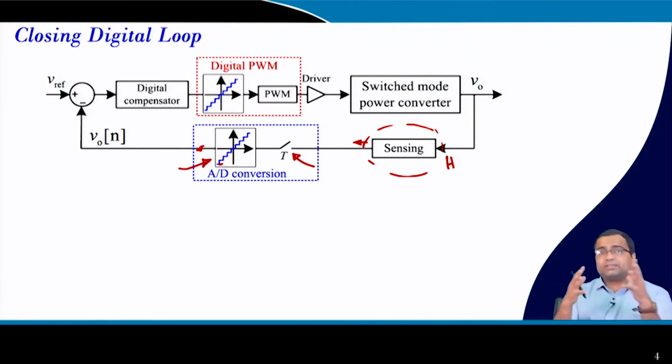So, depending upon different architecture, but in general, for ADC we consider 2's complement. This kind of coding also needs to be considered, because accordingly the output binary number coming out of the ADC will be treated as either 2's complement or offset. If you do not take this coding into account, then you may completely misinterpret the data with the real world analog signal.